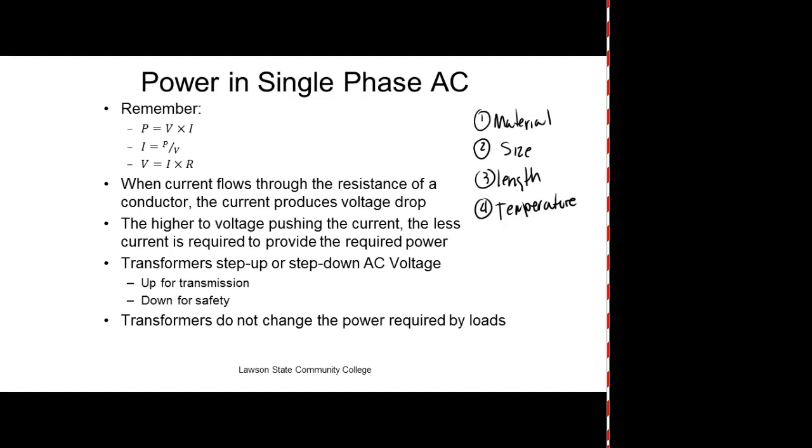And what determines that? Well, it depends on the material you make the wire out of, right? You understand? The size of the wire. So the bigger the size of the wire, the more amps it can carry. We call that ampacity. And then, of course, the length. But you look at American wire gauge, resistance is measured per 1,000 feet. So I think I can show y'all that. But that's at a constant temperature. So the American wire gauge is given at a certain temperature. Usually, I think it's 25 degrees centigrade, which would be about 77 degrees Fahrenheit.